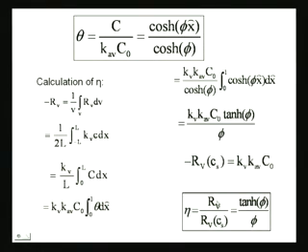Yeah, so this was how we defined our eta, RV over RV evaluated at CS. Now, RV, the general RV, is much lesser because the concentration inside is much lesser. This is something that you need to understand: if there were no diffusional limitations in the system, then your eta is going to be 1. Because of diffusional limitations in the system, your RV is decreased, because the concentration at any point inside the matrix is lower than that at the surface. Because the concentration is lower, and this being a first order reaction, it is different.